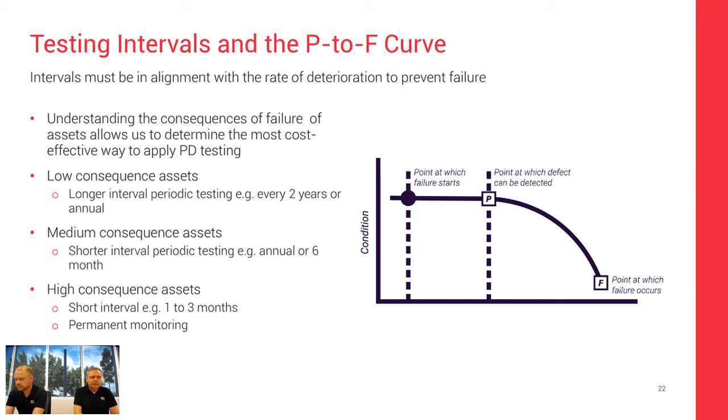As we started moving towards using air insulated terminations, so we started going to dry terminations, more air insulated switchgear, we start moving away from porcelain, going into cast resin and resin type plastic type insulation. We started seeing more and more surface type discharge occurring. At that point, you can get much quicker degradation to failure, particularly if you've got a poor environment. So nowadays, what we tend to say is that there is quite a wide variation. Some failures will take a long time before they get to failure. Some will accelerate quite quickly away.